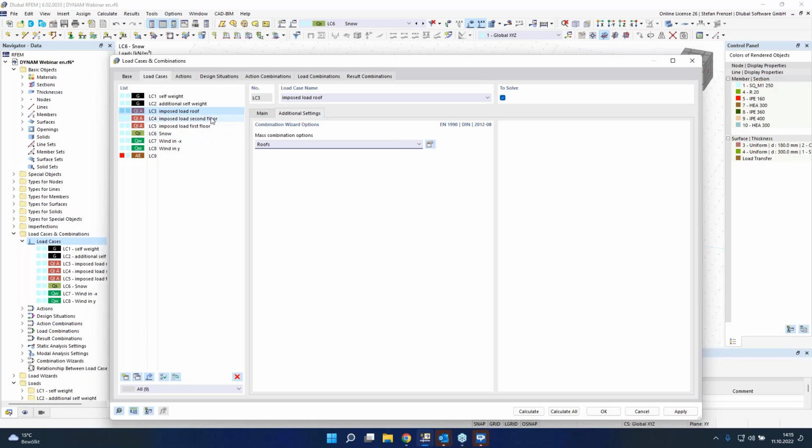And here you see that we have, of course, the additional setting for our load for the roof. Of course, we say that's the roof, and for the second floor and for the first floor it is another floor. If you use here, of course, also the normal standard Eurocode without national annex, you have here also these values and have also some different values for that. So that's just in Germany that you have here, of course, roofs or other floors.